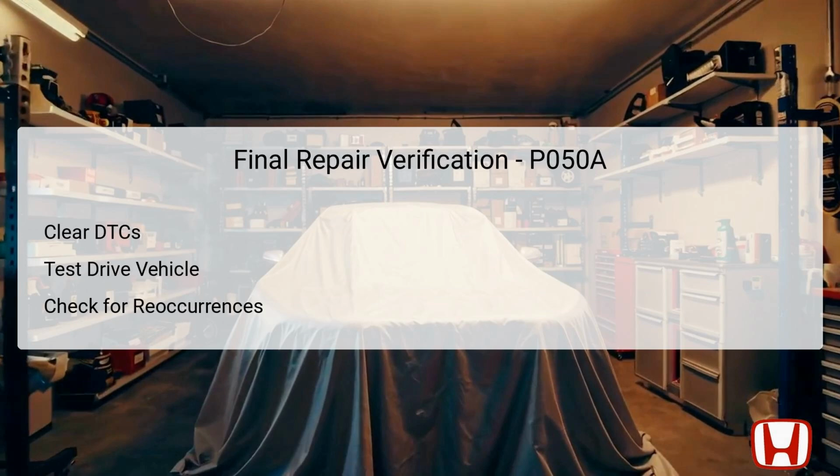After completing all necessary repairs related to DTC P050A, it is crucial to verify that the issues are resolved. Start by clearing all DTCs using the HDS, ensuring that the PCM is reset to an error-free state. Follow this by conducting a test drive to confirm that all systems operate efficiently under various conditions, especially during cold starts. Monitor the vehicle for any signs of stalling, rough idling, or other abnormal behaviors.